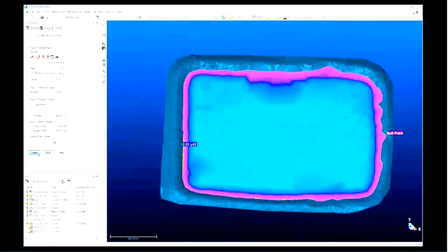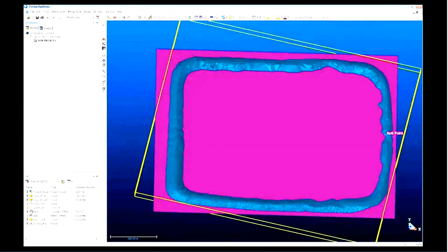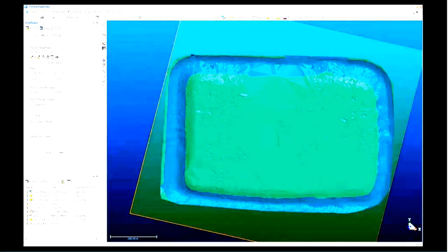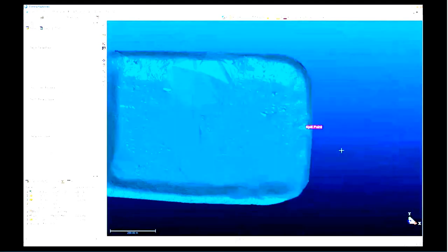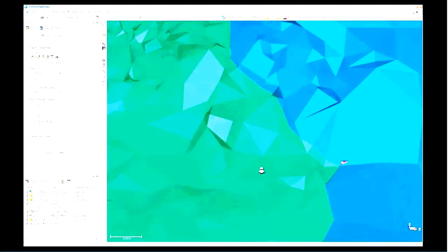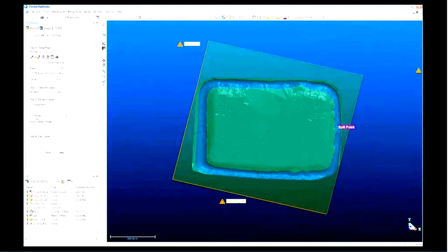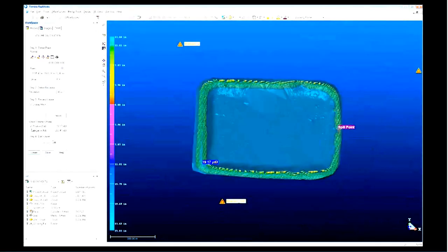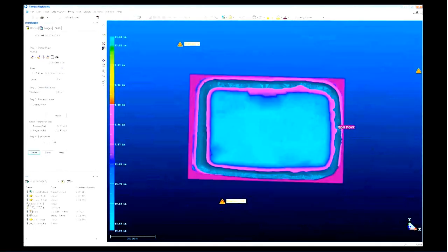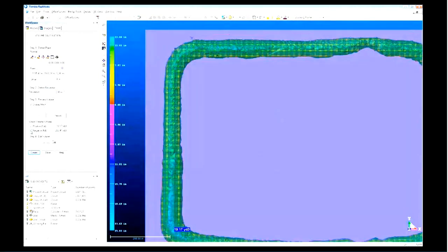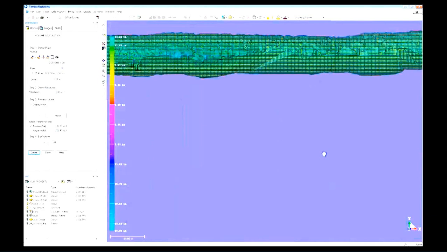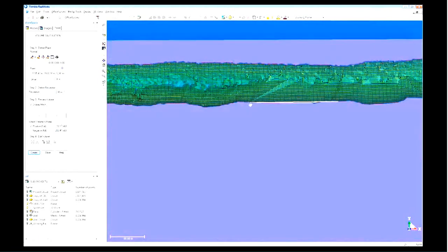Okay, so now I've got a plane. I'm going to use my volume calculation tool now to calculate the volume between that plane and the retaining wall. Just setting a quick resolution for my volume. And I'm picking the plane that I just created, that spill point. And calculating the volume. Now it's giving me the volume overall with this plane compared to the retaining wall.